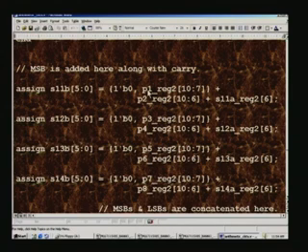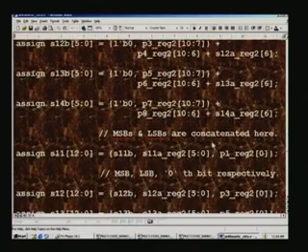These are obtained by adding P1, P2 in this stage and then P3, P4, P5, P6 and the last two here. MSBs and LSBs are concatenated here. So, this is the partial product here, and we have not processed, as I said, the 0 bit earlier. In the partial product of P1, we started only with 1, therefore, we should remember to put that here. So, what we are doing here is merely arranging all the MSB, LSB and also the first bit which was not considered earlier, and we have all of it in the final result of the first stage.